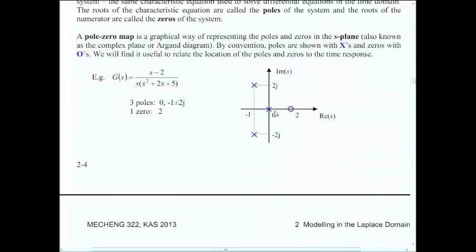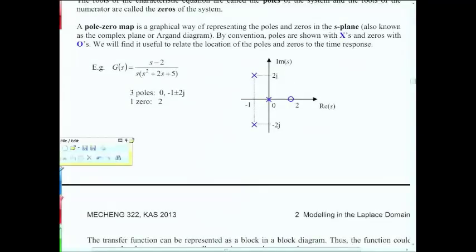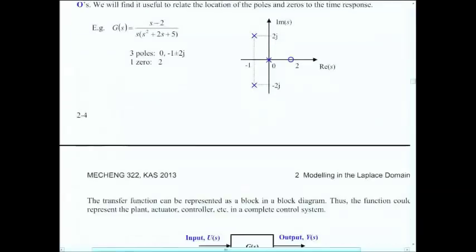I can tell you that it's non-minimum phase because of the zero in the right half plane, which means when you perform an action on it, it'll actually move in the opposite direction of that action before going forwards. All of these things I can tell from my experience of looking at pole zero maps, and you will gain some of this experience in this course. Hence the advantage of dealing with the transfer function and knowing the poles and zeros.